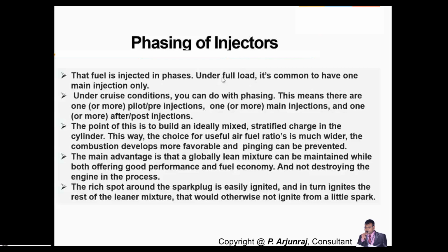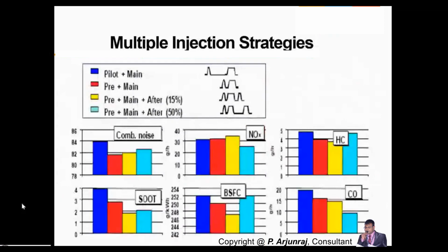How you are going to do the phasing is also very important, because this will have an influence on the emissions as well as performance. When the engine is running in cruise condition, you can do phasing again. This means you again have one or more pilot or pre-injections, then one or more main injections and one or more post injections also. So you need to do the phasing.